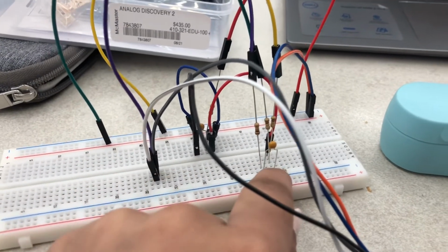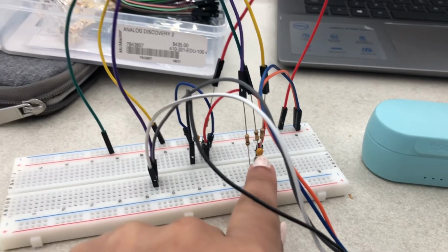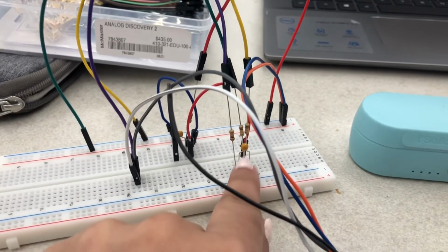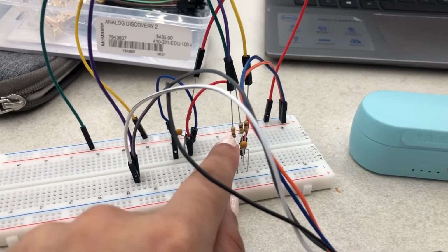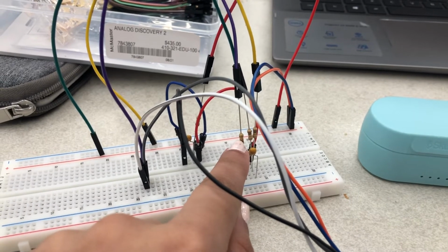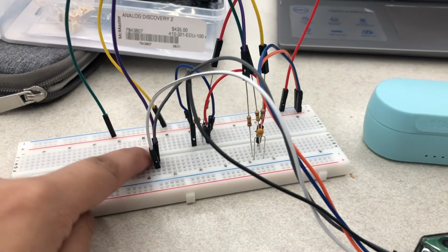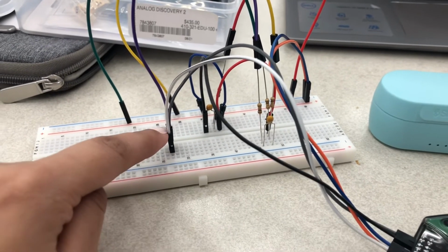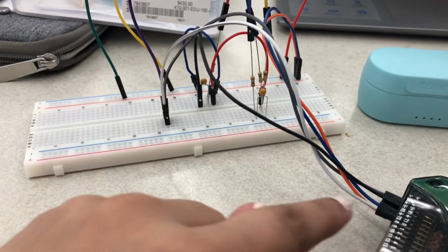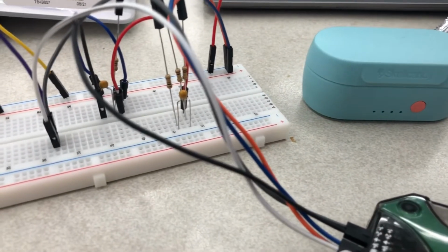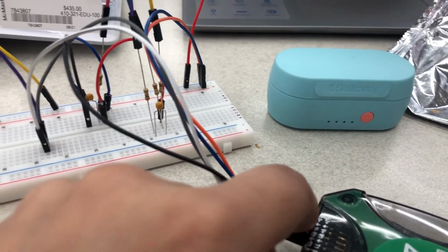After that, you can see that one last node is connected to the base, and it is this 104, which is a 100 nF capacitor, connected over here. This is then connected to this resistor, which is 100 ohms, and that is our RS. It goes all the way following this purple wire to this end right here, and then it is also connected to these 2 wires right here. This white wire follows all the way to W1, and the other gray wire follows all the way to 1+.